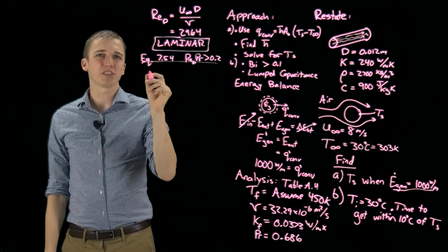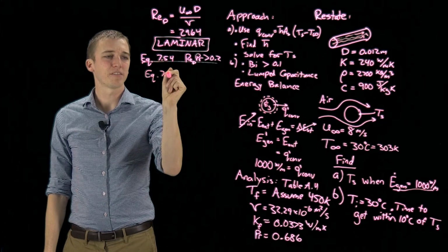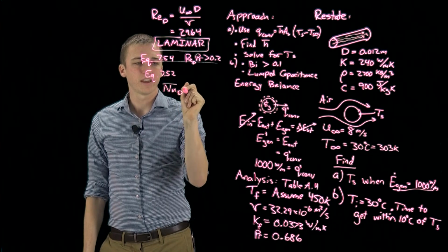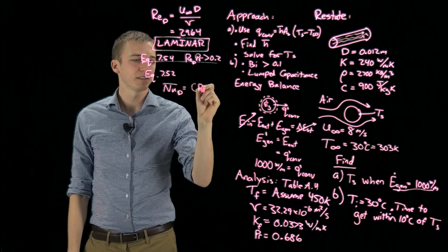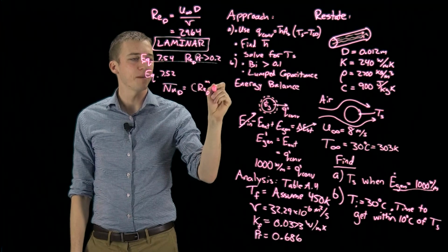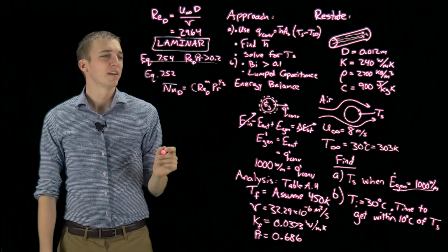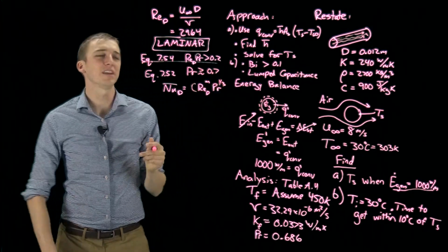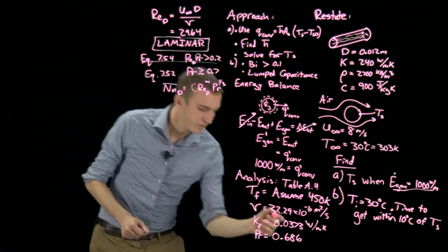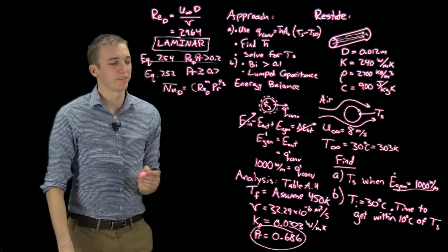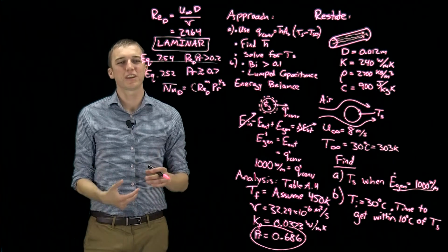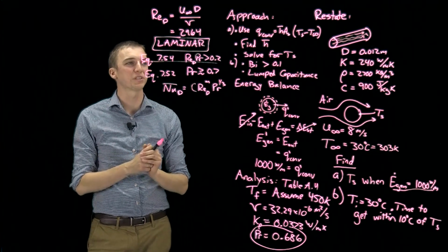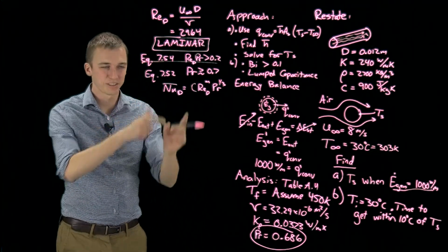However, there's another correlation, equation 7.52. This one is the Nusselt number average is equal to a constant times the Reynolds number raised to m times Prandtl to the 1/3. And this has a single stipulation, which is the Prandtl number must be greater than or about equal to 0.7, which you will notice we violate that by just a tiny bit. Because we're just on the cusp, I'm going to say this is easier, if anything, because it would take a significant portion of the board to write the other correlation. So we're going to use this one.